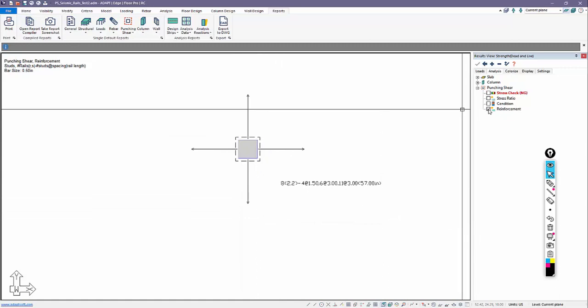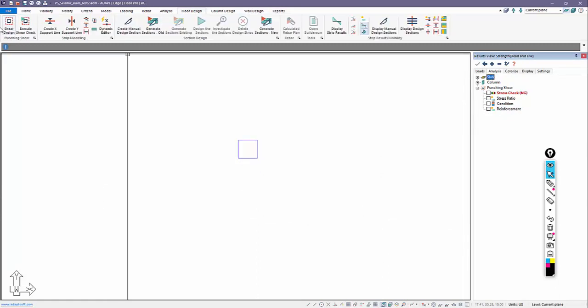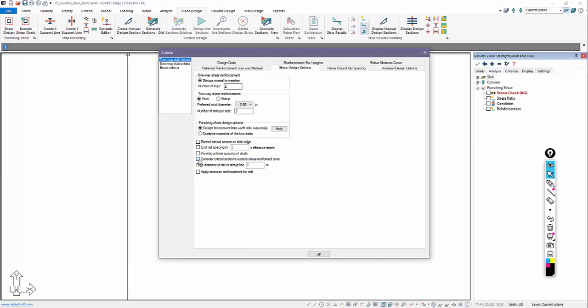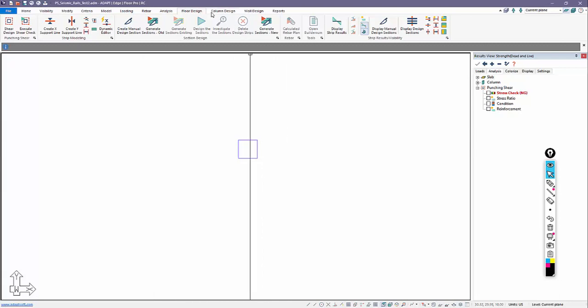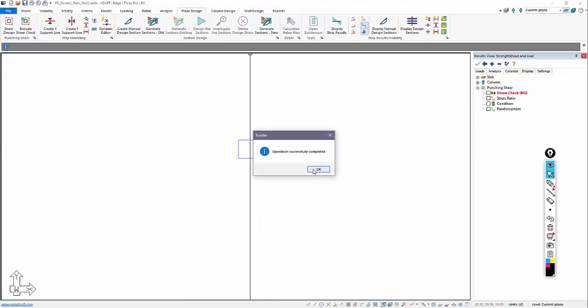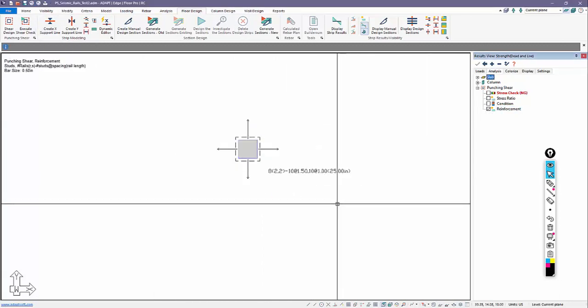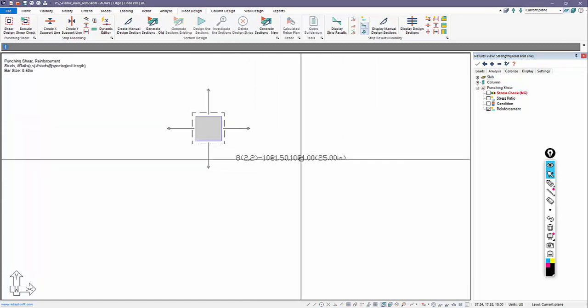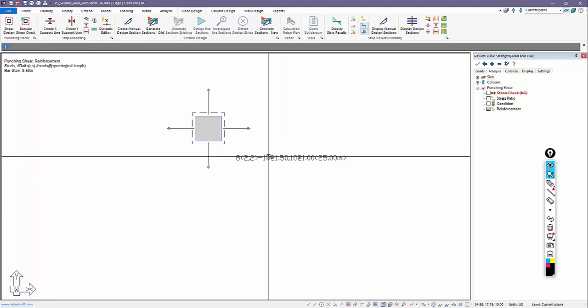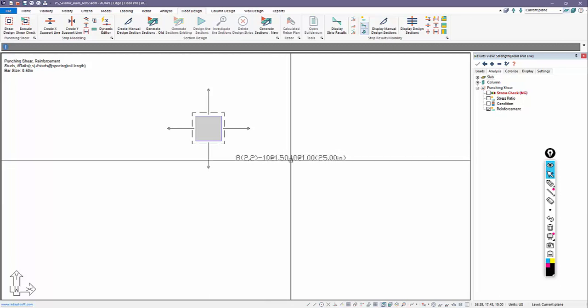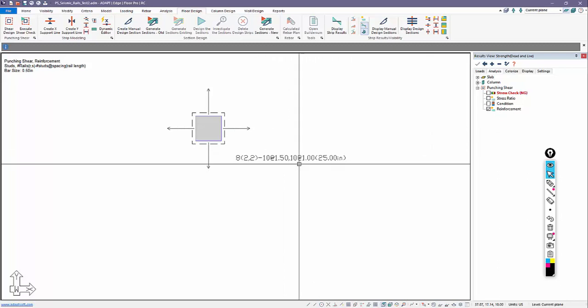Now what we'll do is we'll look at the drift check. So I'm going to go ahead and turn off the octagonal check just for a moment. I'll go back to drift check. Looking at our control sample, we said we needed 10 studs. That's the baseline that we're comparing to. If we go back and we execute again, you can see we need 10 and 10. So in the first example, we actually needed 4 at 1.5. Now we need 10 at 1.5 in order to maintain that distance 4 times h.